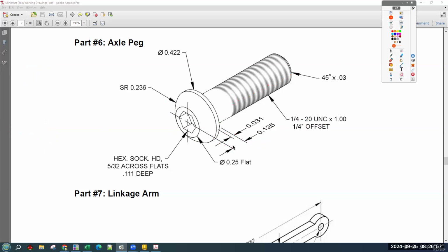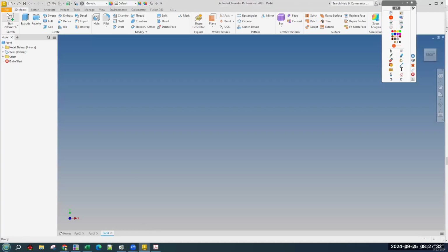Okay, if you can see these extension lines, this extension line is measuring to the start of the peg head. Then the distance between here and here is the size of the flat part. And if you follow this 0.125, this is its corresponding dimension arrow, and you can follow that along. It's the top of the entire surface. So after all that, we have figured out that the total height is 1 inch plus 0.125, otherwise known as 1.125. And that'll give us our first line.